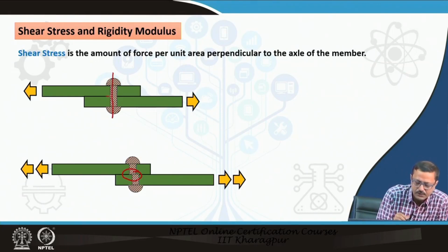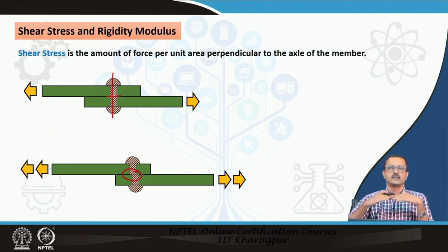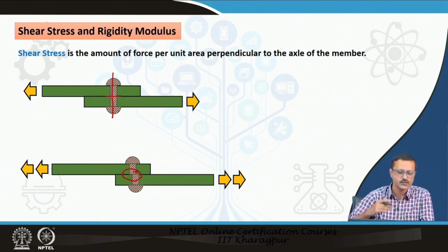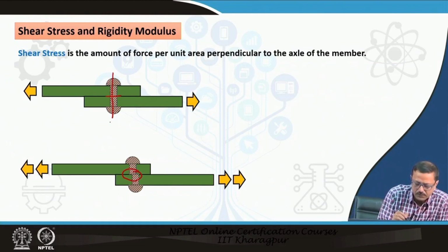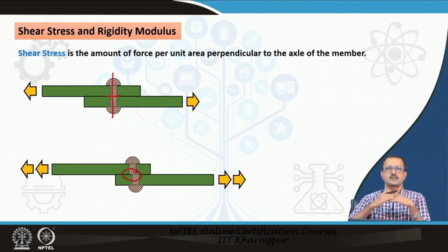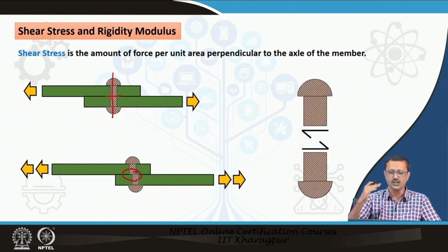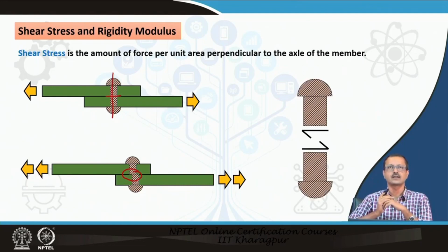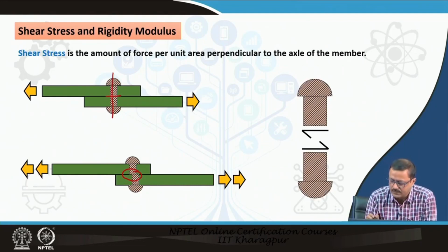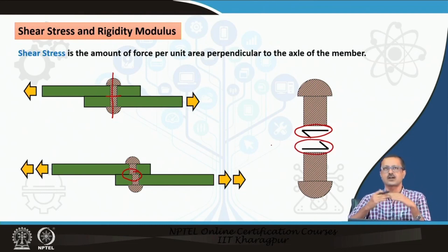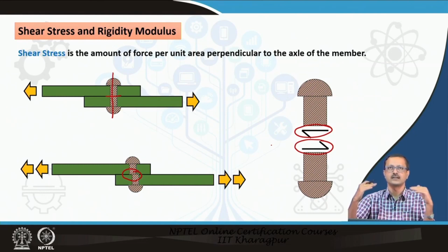This particular plane fails because of the shearing force, applied perpendicular to the length axis, and it is a kind of slicing force. So, we can say that this rivet or nail fails because two equal and opposite forces are applied on a particular section in between the lap material, and it is going to fail.